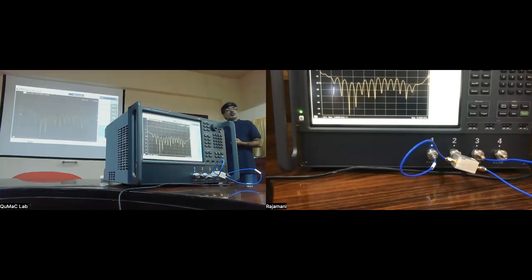But if the frequencies are the same, the phases could still be completely random, but you could then have a situation where you have a precise phase relationship between the 2 signals. In that case, if these 2 are exactly in phase, then the total power coming out will actually not have that loss.